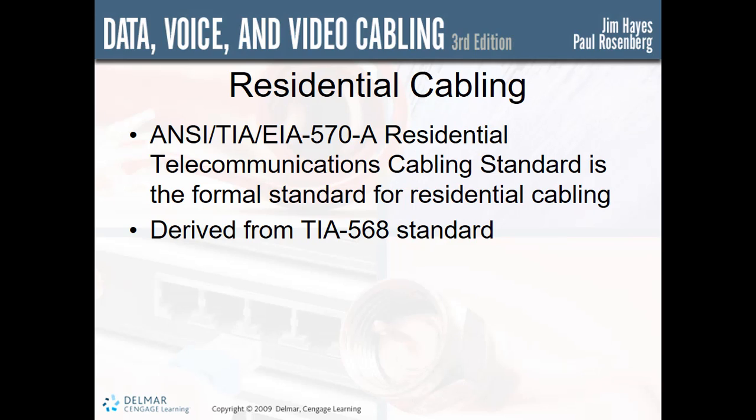Grade 2 outlets: at least one outlet must be provided in each kitchen, bedroom, family room, great room, and den or study. It is recommended that one outlet be provided for each 12 feet of unbroken wall space. The 8-position modular jack is the only UTP jack allowed for the outlet, and it must be wired in the A configuration. The 6-pin RJ11 is not allowed, and additionally, splitting of pairs is only allowed with an external adapter.